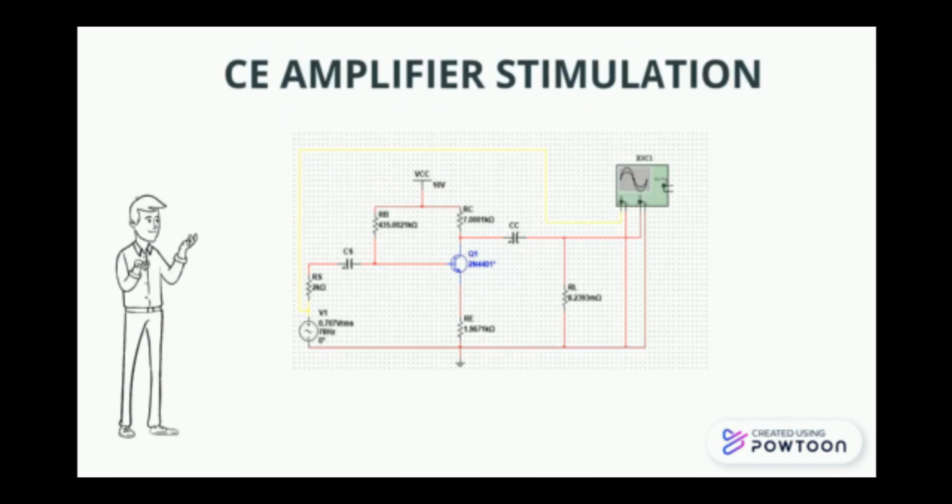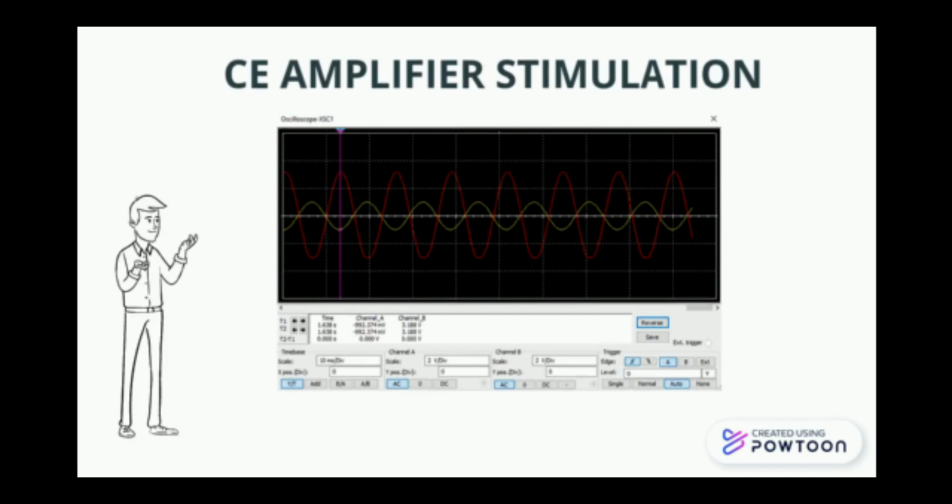By connecting the oscilloscope probes to V in and V out, we can find our frequency. Now we can see the frequency from the oscilloscope. As we can see, the red frequency is V out, while the yellow frequency is V in. The red frequency has a 180 degree phase shift from the yellow frequency.